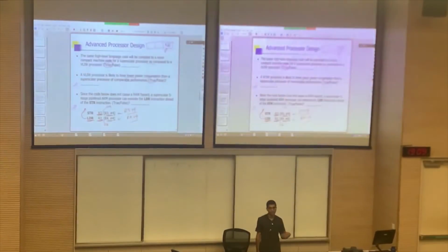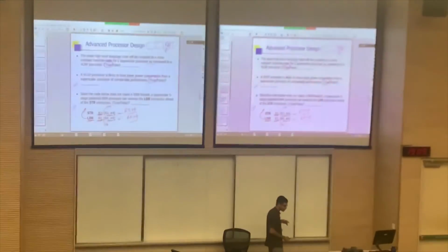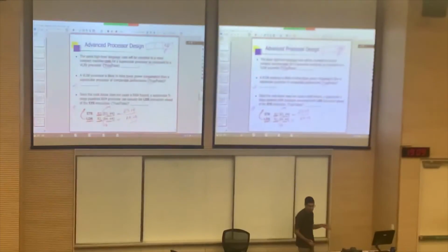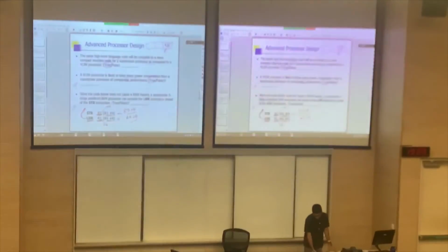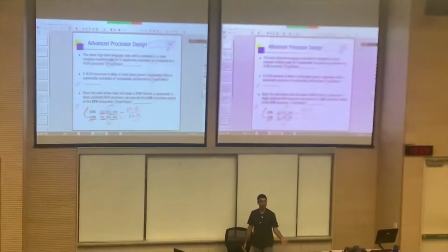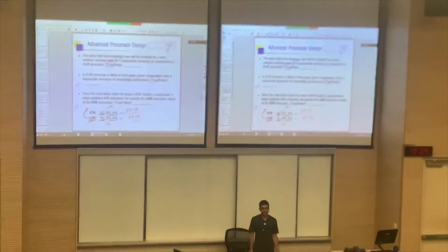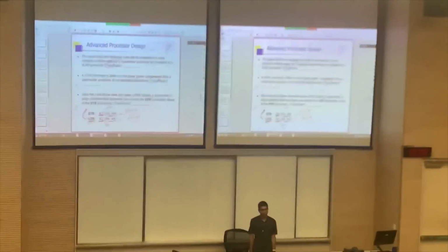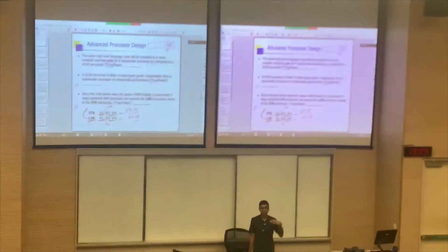That is called load speculation. This is done by a superscalar processor at runtime. It can make this assumption, and that will allow the load to be scheduled earlier. Load being scheduled earlier is beneficial because if a load causes a cache miss, it can cause a huge penalty. So by pushing it ahead, you can hide some of those possible cache miss penalties.